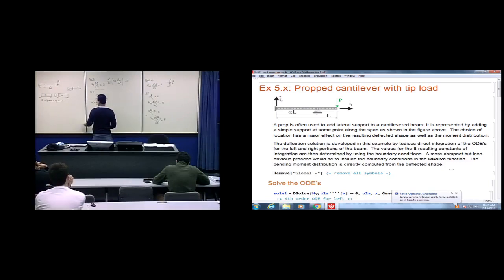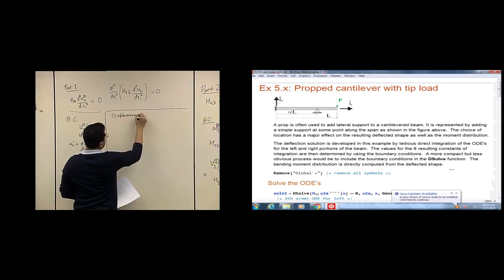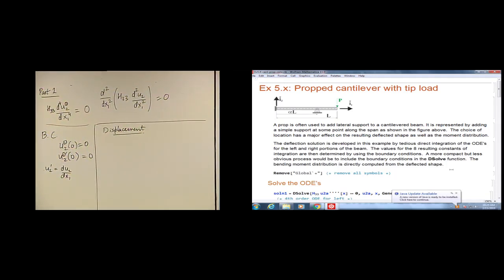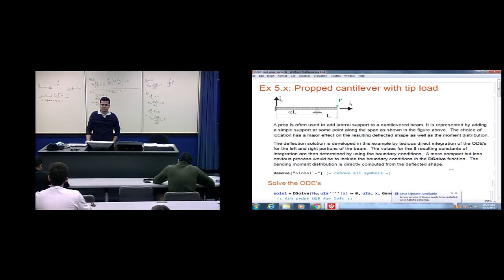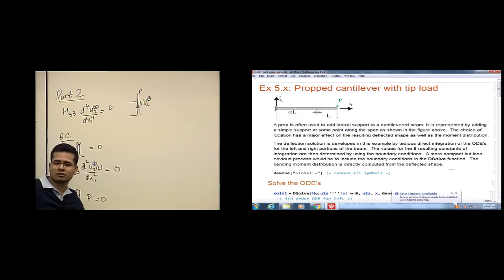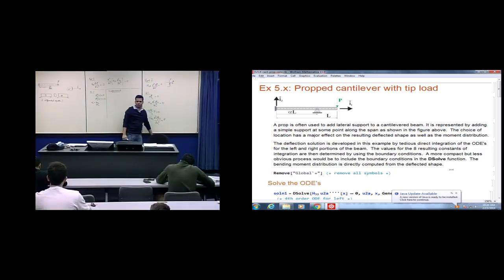So let's think about what's happening in the middle. We'll start with displacement. So any idea about the displacement? I'm just explaining that the reason there's shear at the end of the beam is because the shear will be up and it's going to be canceled out by P, and then the sum is 0 at the end. So we are applying the equilibrium at the right end, and there should be some shear force V2, and P is applied. So we are just doing an equilibrium. If the P was not there, we'll say that shear force is 0. So that's standard, we already know, right?